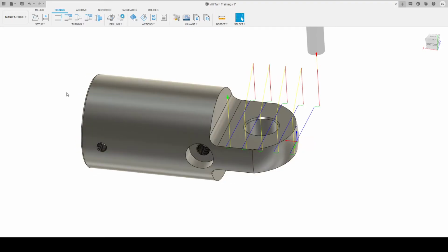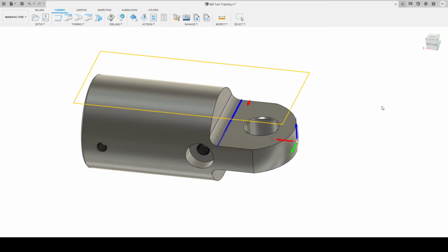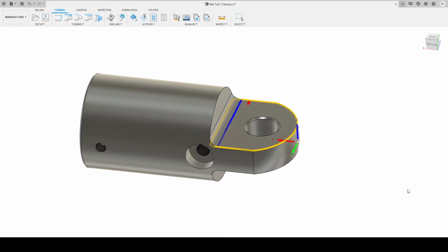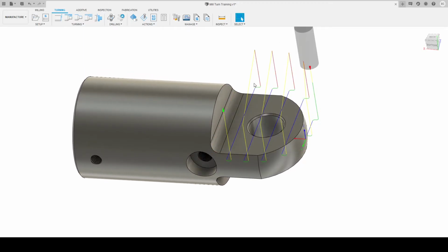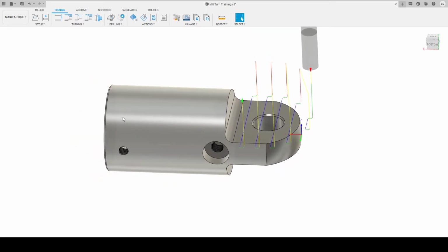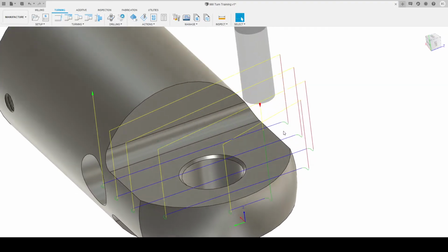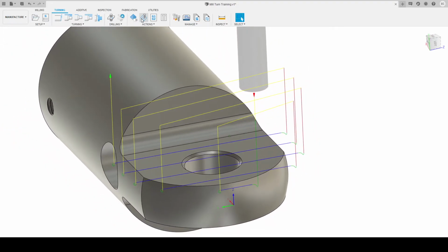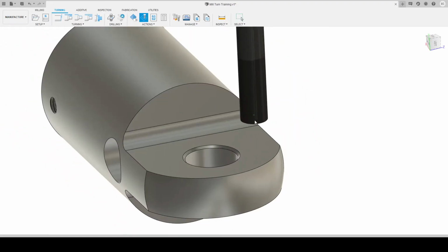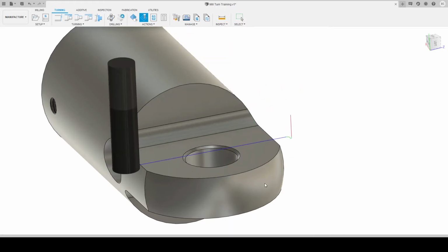So we can define that if we edit our toolpath, jump in and turn stock contours on, and then only select this area. It'll sort of start trimming our toolpath to only cut the stock that we selected then. And another thing, we want to see how it's coming in and turning, and it's sort of leading in on the part. If we turn our stock off, it's leading in on the part. We'll jump forwards a bit.